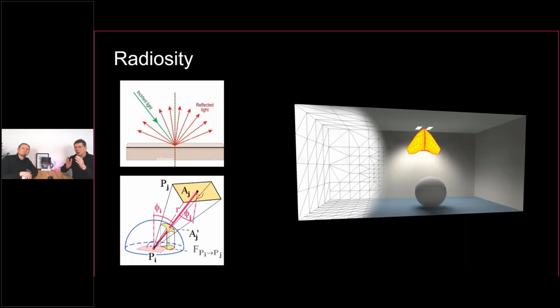And here we are now at a radiosity calculation, the radiosity calculation core. The essential thing here is that in the first step of the calculation we calculate the direct part from the luminaires to all points in the room. So each calculation point on the room surfaces represents a patch, which will later be used in the indirect part for the reflection of the light. This works only when we have a diffuse reflection on our surfaces.